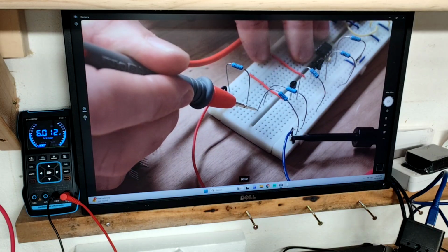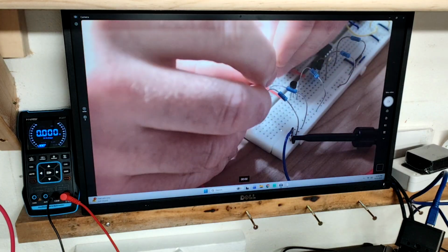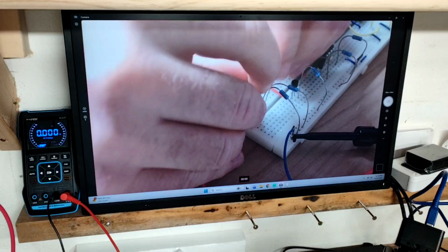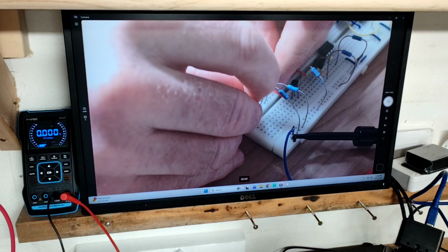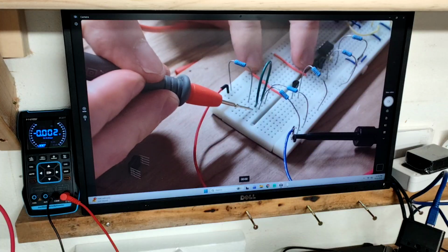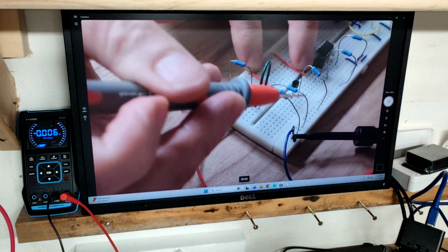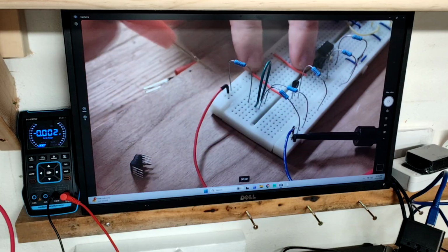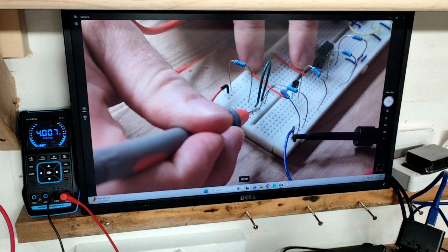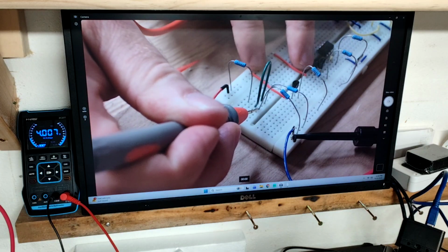Now, that's fine, but what happens if I try to use that for something? Let's say I put this wire in here to take that signal and run it through some load. I have another one of those resistors there. So now I'm taking that voltage here and running it into this resistor, which is putting some load onto the negative rail. So now what do we measure here? Now we only measure 4 volts, right? So we've completely destroyed that input signal.